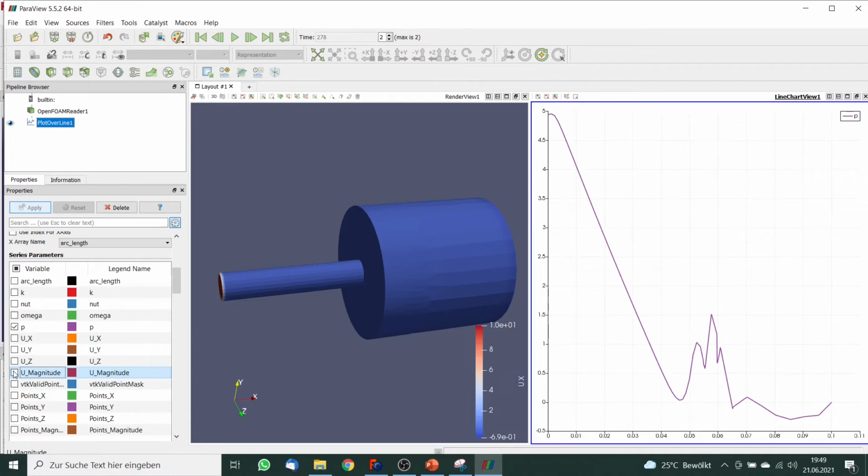So what you see is that here we have a higher pressure on the incoming side. It's this specific pressure. This is 5. But what you see is that the loss from this point to this point is nearly equal to the analytical model. What has changed is the loss due to the diameter shift. The calculation showed much less losses. And on the right side, we go to 0. So 0 was our boundary condition.